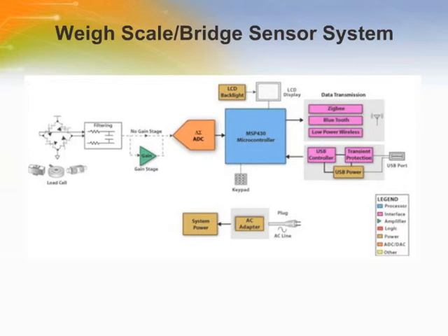The key role of the instrumentation amplifier is to amplify the very small differential input voltage and reject the common mode input voltage. But for the best performance, the instrumentation amplifier must have excellent long-term stability with regards to offset drift and gain, because real-world sensors have span and offset errors that are ever-changing over temperature.